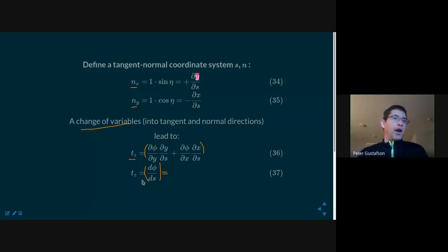This is the same argument that we said we're going to treat the beam resultants as being the total force at the end of the beam, as opposed to looking at the actual stress at a point in the beam. Now, of course, you can calculate that. We could, but that's not what beam theory strives to achieve, nor is that what shaft theory strives to achieve here. Shaft theory is really nothing but beam theory applied to torsion problems.